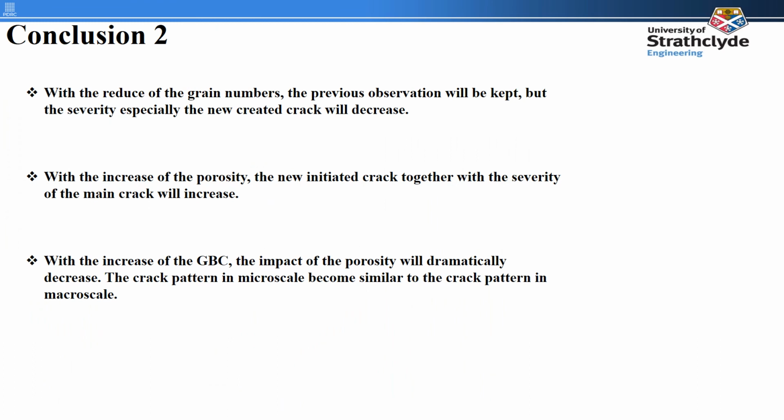In conclusion, the severity of the crack, especially the newly created crack, is positively proportional to the grain numbers and porosity. For the grain boundary strength, with the increase of the grain boundary coefficient, the influence of the grain boundary will decrease, and the fracture becomes more similar to the macroscopic pattern.